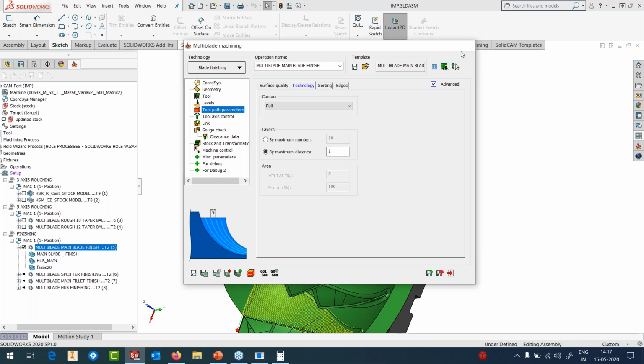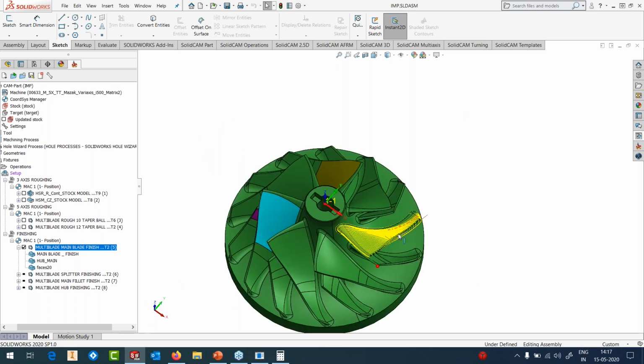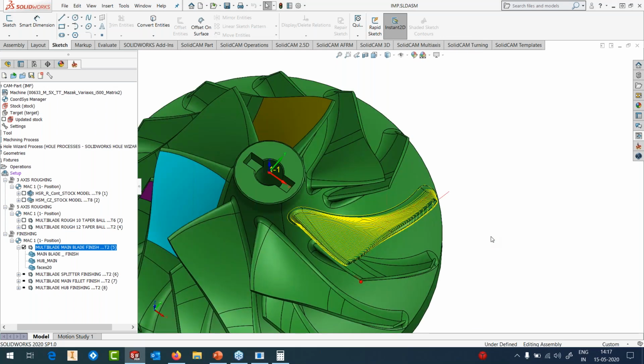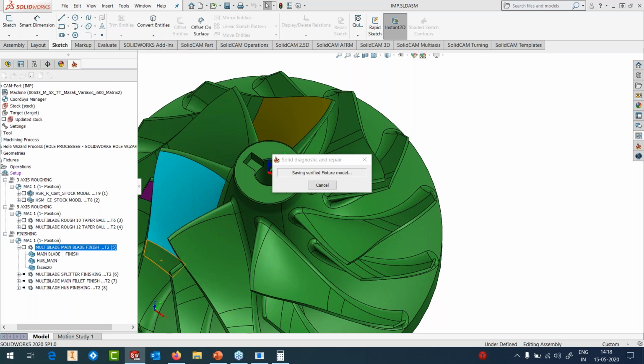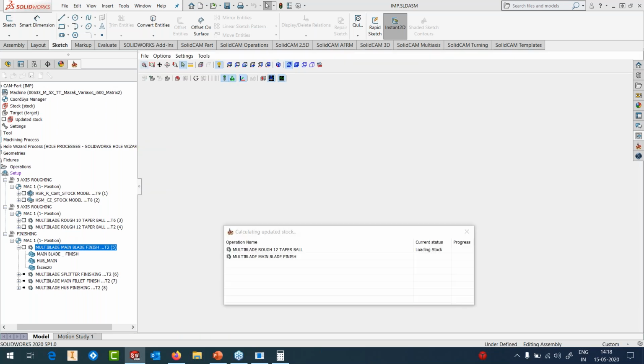Toolpaths anyway are taken care of by SolidCAM. Okay, so finishing is done. It's simply running like a spiral, starting from the edge, from the start, and going all the way down. So if I run the simulation, the finishing can be done in two ways. The finishing can be done using multiple cuts, or you could do swarfing of this function with a single pass. But in the majority of cases, the impeller surfaces are not classic or ideal for doing swarfing.